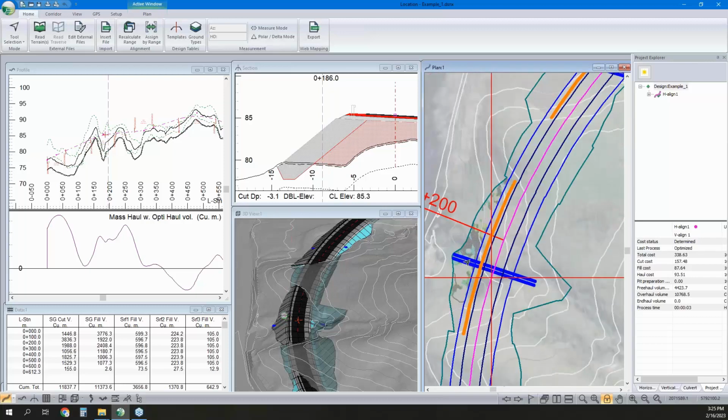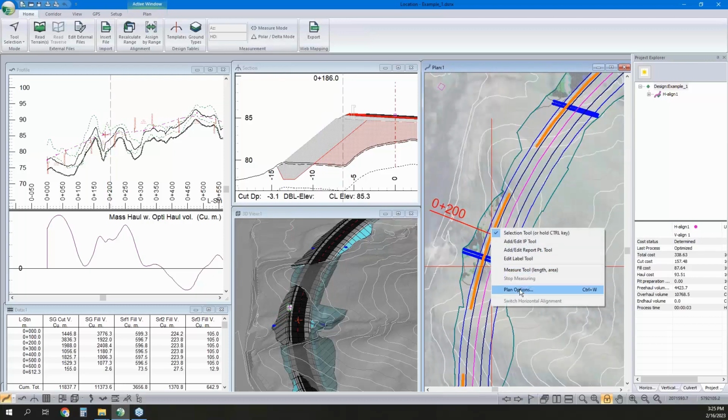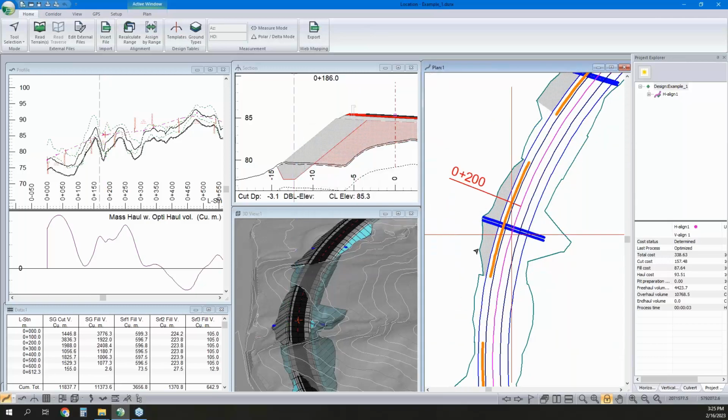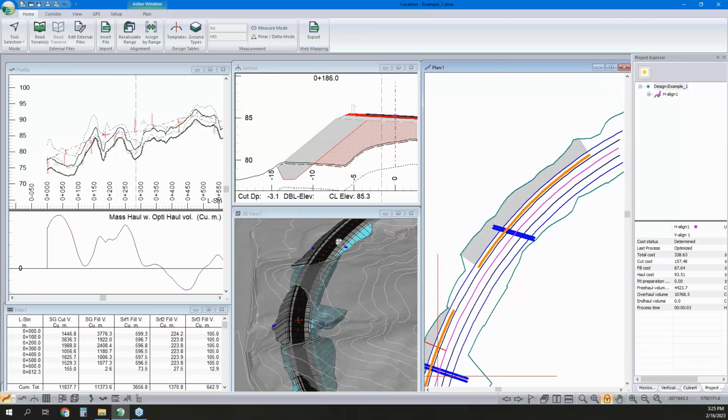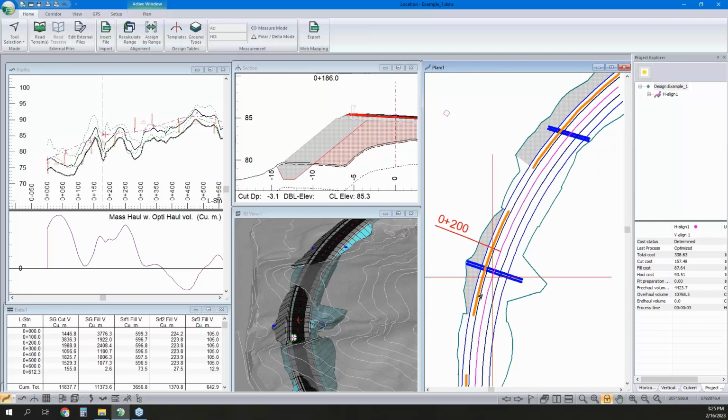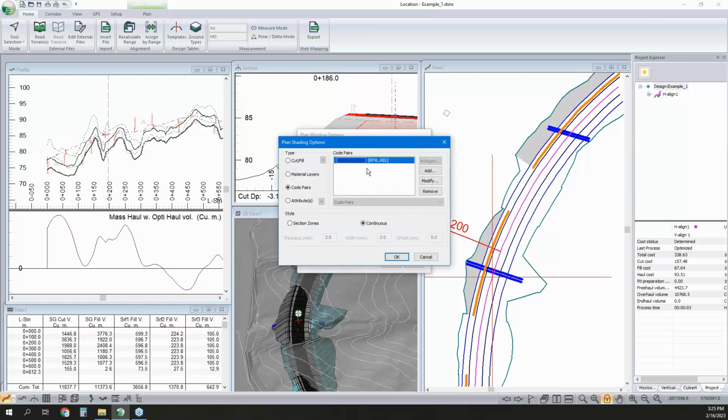So I've got that showing up as being hatched. And let's just turn off our background here so it's a little clearer what we have going on. We don't have all that other stuff being busy. So we can hatch between our point codes, and the point codes are similar to how we set up the guardrail setting.